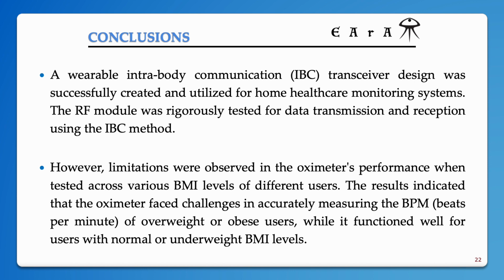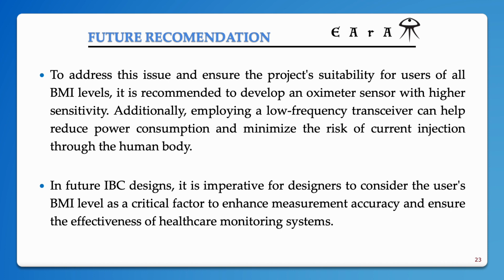study this further. Okay, for future recommendations to address this issue, to ensure the project's suitability for users of all BMI levels, it is recommended to develop an oximeter with higher sensitivity. This is one option. Additionally, employing a low frequency transceiver can help reduce power consumption and minimize the risk of current injection through the human body. So our main recommendation for future IBC designers is that it is imperative to consider the user's BMI level as a critical factor to enhance measurement accuracy and ensure the effectiveness of healthcare monitoring systems using IBC.